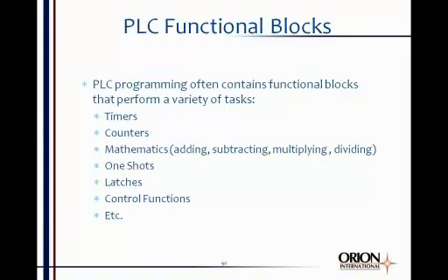Now, modern PLCs also contain what are called functional blocks, and these functional blocks do a whole variety of tasks. You can get functional blocks that will do timers, counters. You can get mathematical operating functional blocks. You can get what are called one-shot functional blocks. They'll fire once, and then that's it. You can get latch functional blocks. You can get all kinds of control functions like integral and derivative control, PID control. There's a lot of different types of functionality built into modern PLCs. You can really do a lot with them, and sometimes the programming can get very complicated as well. They generally send you to school to program a PLC.